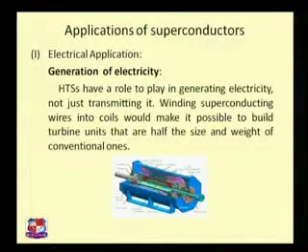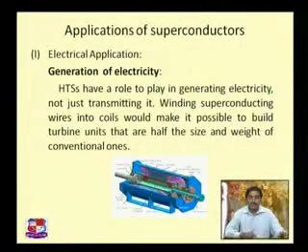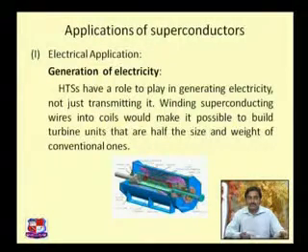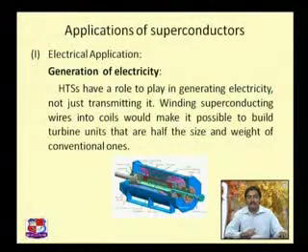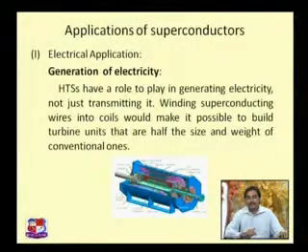This is one diagram, shown there with the components mentioned. If you see carefully, within the generator we have liquid helium passing through tubes, which takes out the heat energy produced during the generation process. As the temperature decreases below the critical temperature of the material used for making the coil, it is converted into a superconductor, or gets a state of superconductivity. So there won't be any resistance available, and due to that there won't be any loss.